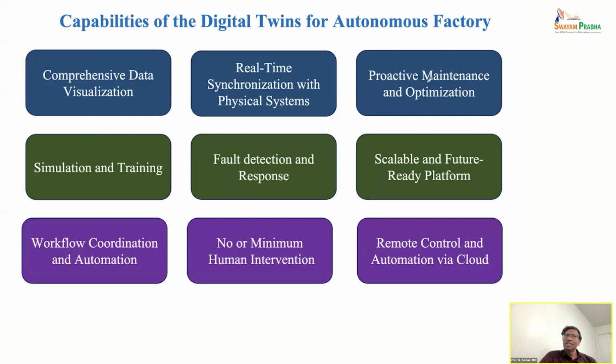Then see, we used to talk about different types of maintenance. Earlier, it was what is called breakdown maintenance. So you run the machine till it breaks down. When it breaks down, you go check what has failed and then replace. But nowadays it is not recommended, because when it fails, the whole process needs to stop. Sometimes if you are working with very lean stocks, once you stop, the whole process needs to be stopped. Nowadays we are not keeping a lot of stocks, but we run on lean manufacturing kind of systems. So that means in breakdown maintenance, you cannot follow.